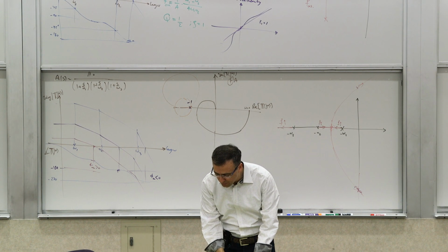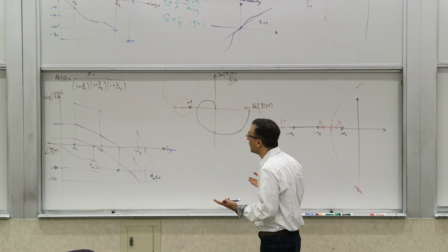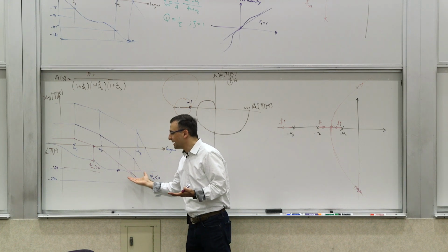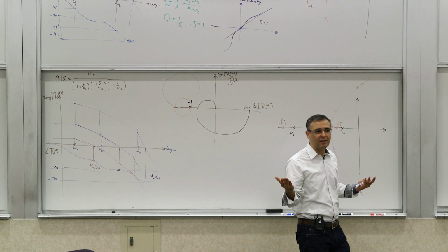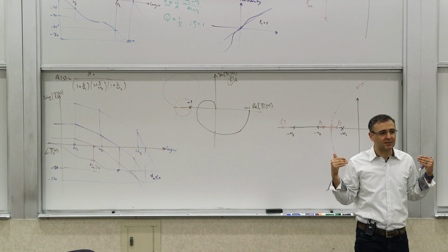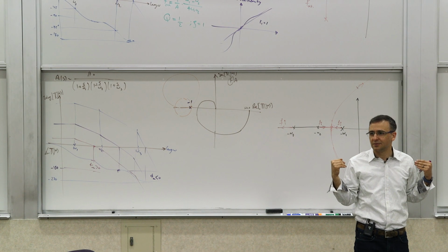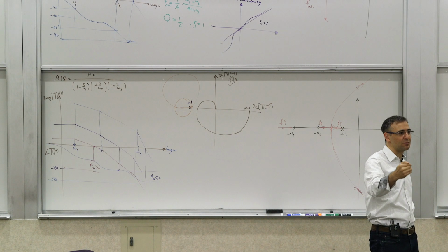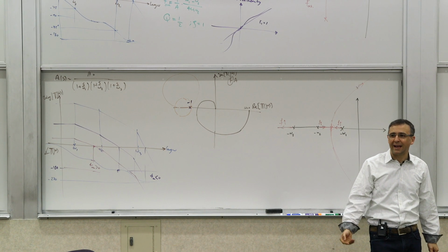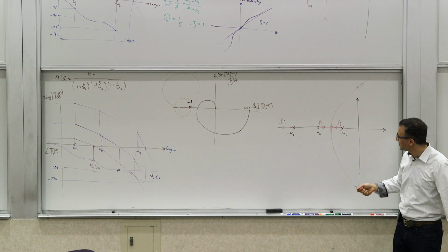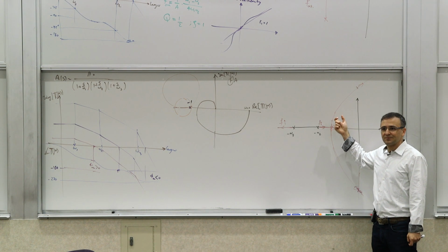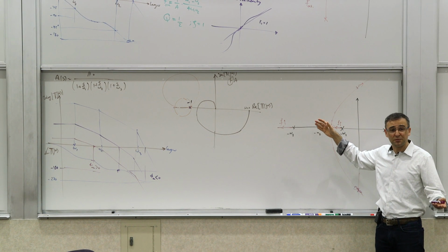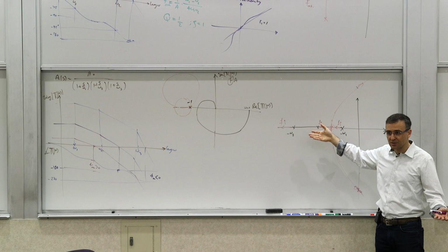So you can see now that for a system with 3 poles, you can easily get instability. Go back to the circuit example we started with, for stability. You remember there were 3 capacitors, 3 poles. We had 3 real poles initially in the open loop system.